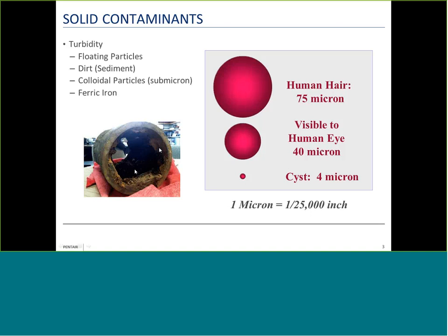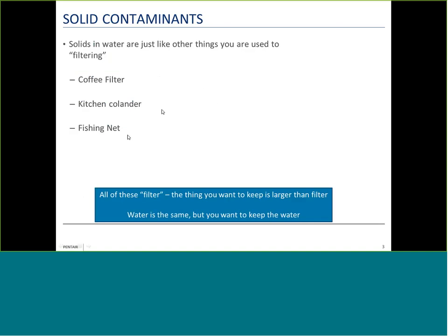Now, solid contaminants in quick change filters are going to range from a half micron, which is about here, and larger. And when we get up in the 5 to 10 micron range, we're really talking about particulate removal with pre-filtration. And below that, below 5 micron and below, we're kind of dealing with carbon filtration, not only to do chemical removal, but also potentially bacterial removal at half micron levels.